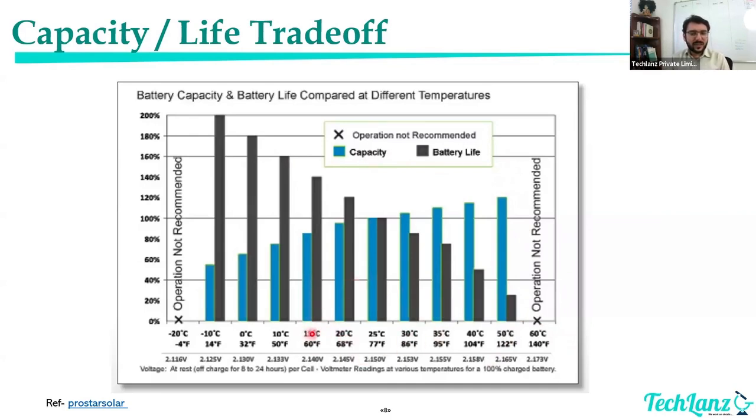The trade-off zone is between 20 to 30 or 35 degrees, depending on chemistries like LFP, NMC, sodium ion or solid state battery. This temperature zone changes, especially for solid state, where it is much higher. We'll talk about it later, right? So you have a sweet spot where you should be operating your batteries.